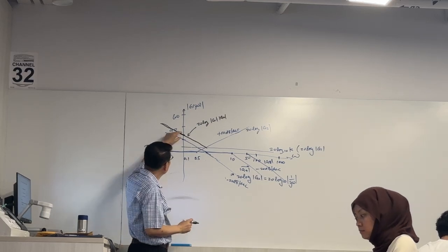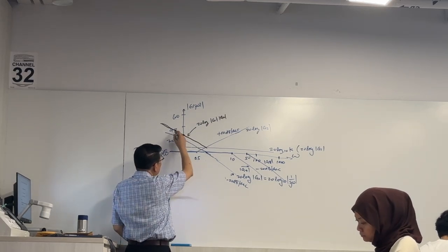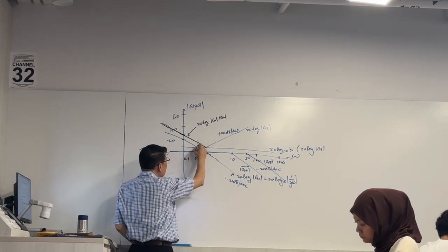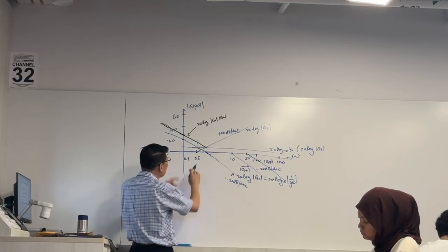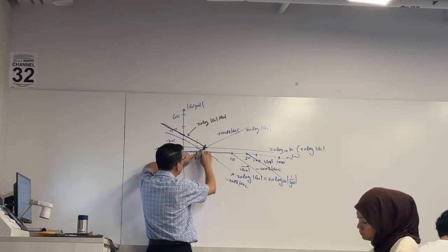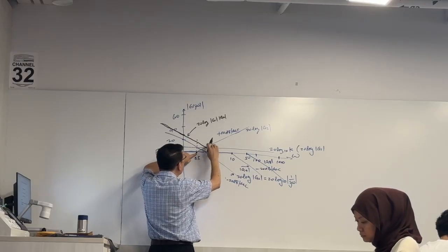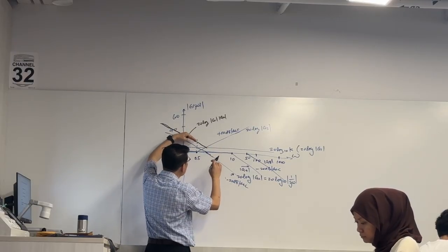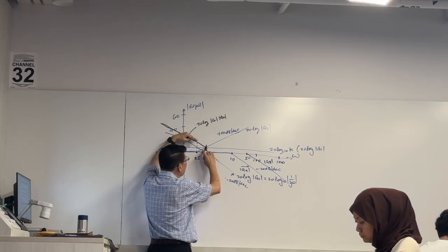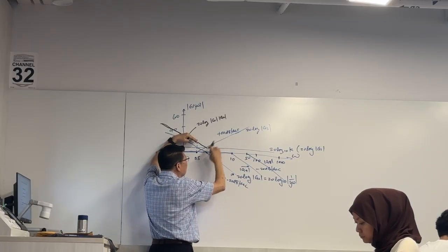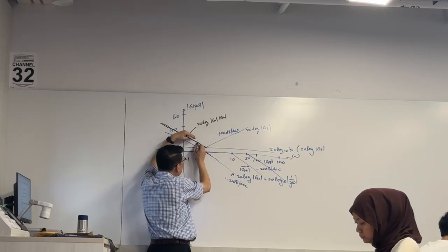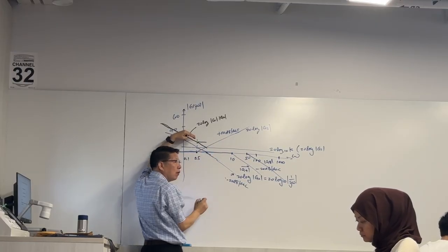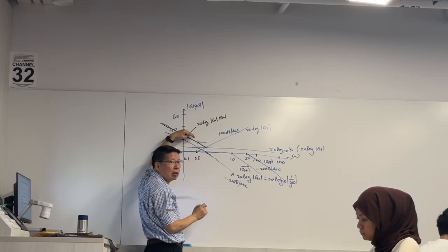Okay? You get this one, and it will come all the way until you hit the first corner frequency. At this new corner frequency, you have the new contribution. So the original is a minus 20 dB per decade. Now this gives you plus 20 dB per decade. Then they add up to 0 dB per decade. So flat. Alright?